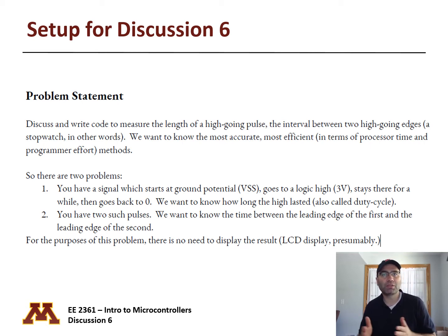One is, we start low, then the logic state on the pin goes high, and then it goes back to low again. We want to know how long high lasted. If you know the period and how long high lasted, then we can easily find the duty cycle.